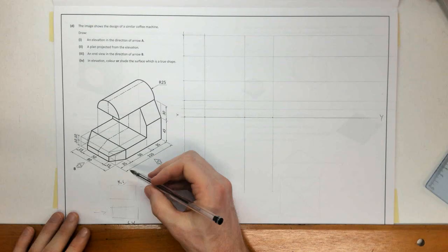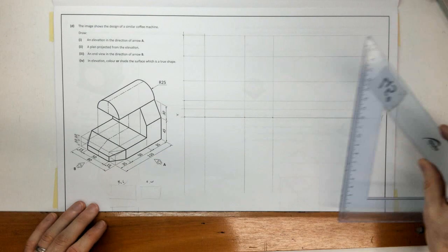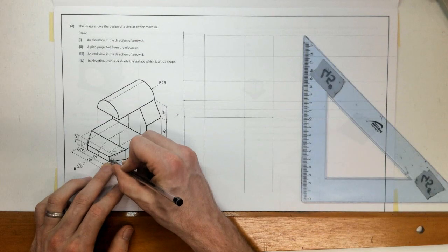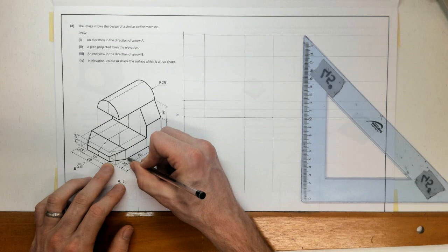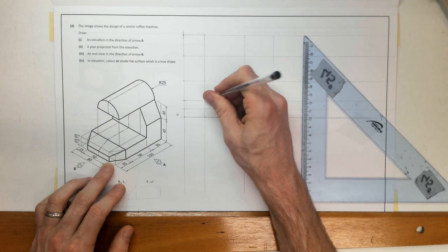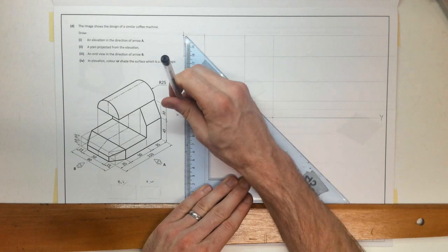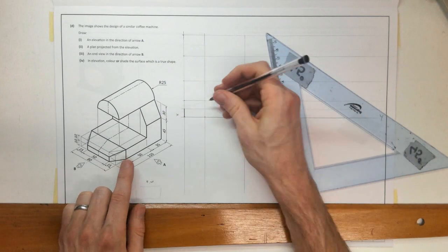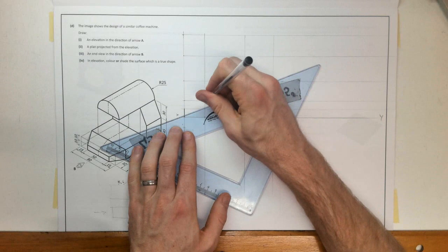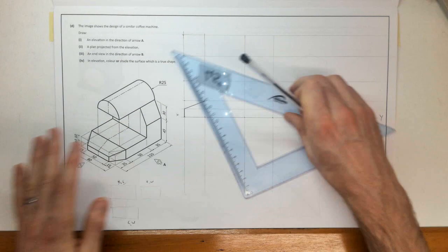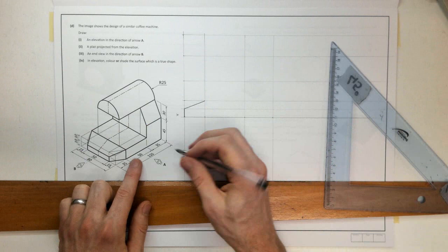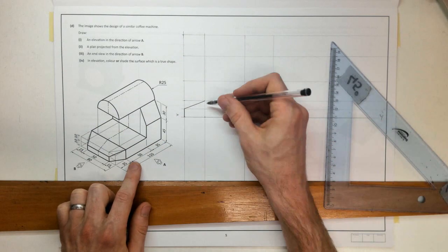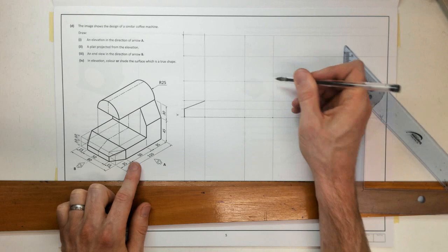So let's draw what we can see when we're looking from A. I've got that front edge of 10, and back here, then back 25 goes up to the height of 20, so just 10 plus 10. And we're going to have an outline then, this L kind of shape, or reverse L. So that's coming across and up to here.